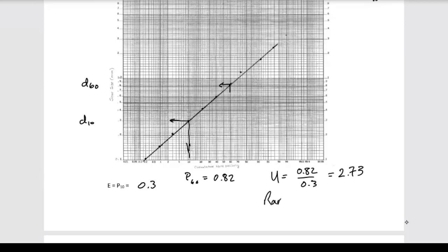This value should be between 1.3 to 1.8, and the GLUMRB standards state that it should be less than or equal to 1.65. Basically, so it's more uniform. What do I do now? I'd have to go back to the company, the supplier of the sand, and say that I need a sand that meets this criteria.